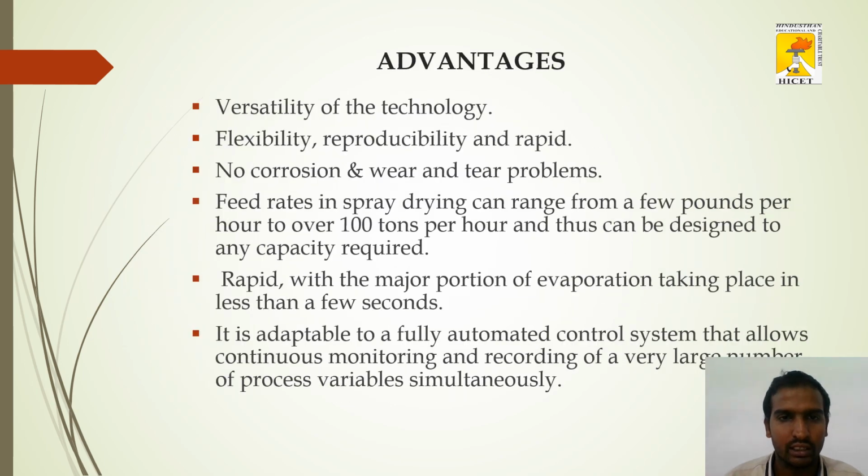And advantages. The spray dryer is a versatile technology and it has flexibility, no corrosion, no wear and tear, and you have exact feed rates and exact production of powders, good in quality, and rapid evaporation taking place, with less drying time compared to the others. If you are using a drum dryer, the conduction type of heating takes place, but the quality of the product may be questionable.